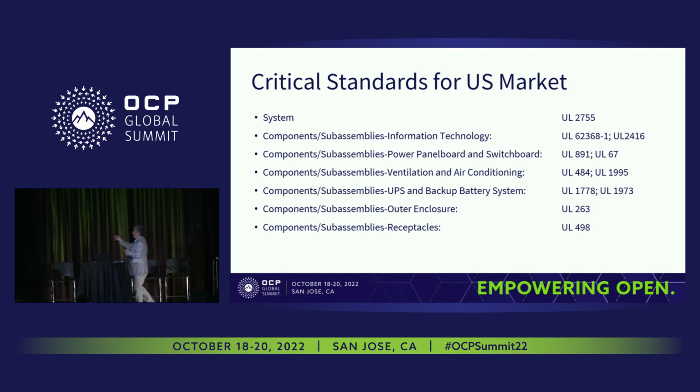Those of you that are not from the United States are probably noticing that there's only UL 62368 that resembles an IEC standard. Everything else is US specific. So if you're sourcing a UPS from a supplier that is in Europe and they have a certification through the EN standard, make sure you tell them we need certification from the United States as well.